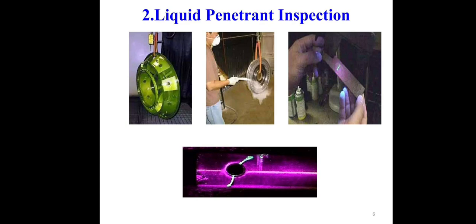Application of liquid penetrant inspection: inspection of tools and dies, inspection of tanks, vessels, reactors, piping and pumps in the chemical, petrochemical, food, paper and processing industries. Inspection of diesel locomotive, truck and automobile parts such as axle, wheel, gears, crankshaft, cylinder blocks, etc.